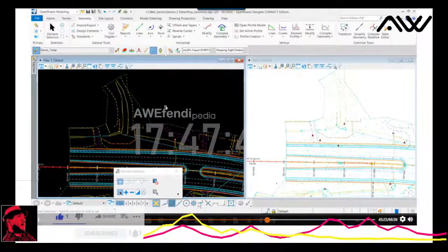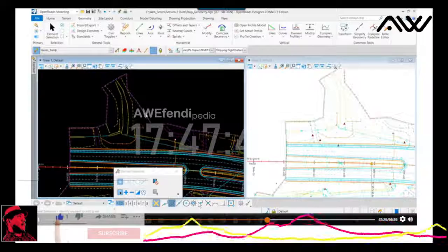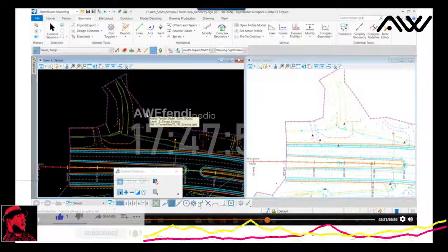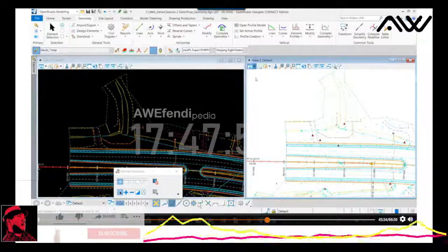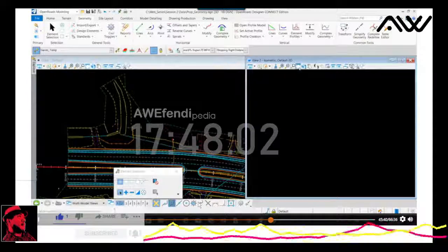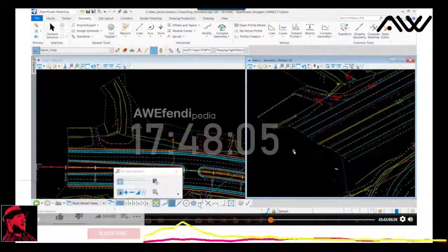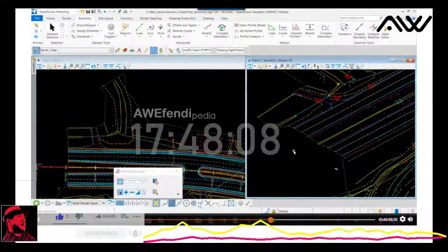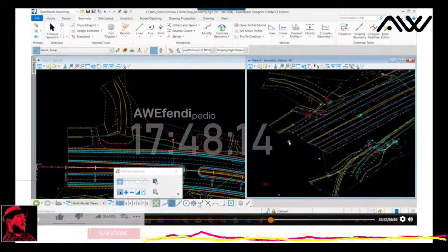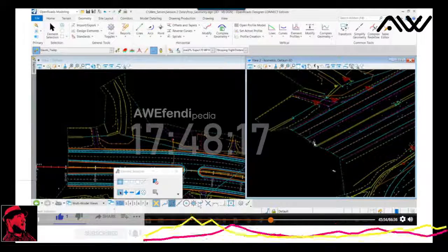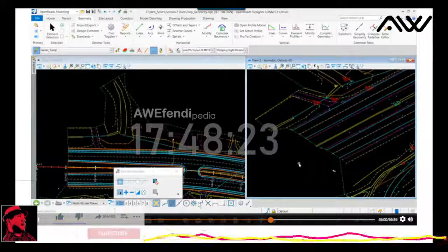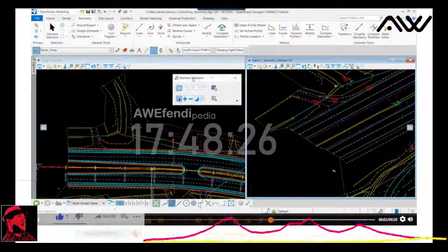That sets the terrain model active. Not only does it set the terrain model active, but by activating any design element that has 3D in it, meaning some sort of elevation definition, OpenRoads Designer also moves all of the project data into a 3-dimensional model. So now the data that I referenced to my original 2D file has been placed in a 3D model as well. So the elevations from my topo, the elevations from my resulting terrain model, all that data is in a 3D model in my DGN and available for me to use.